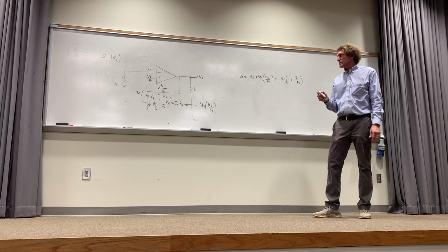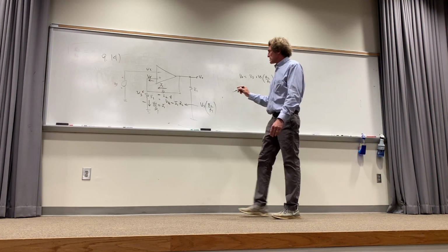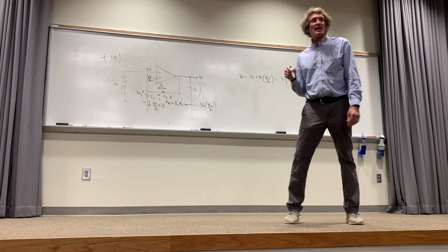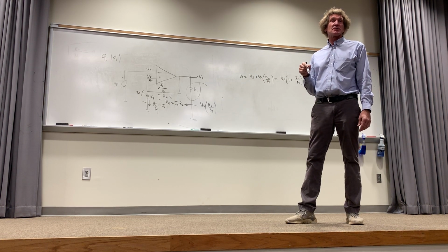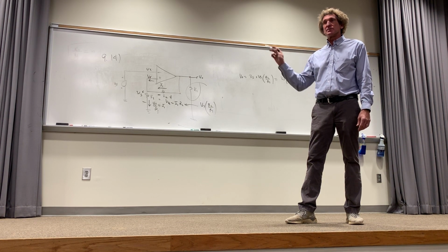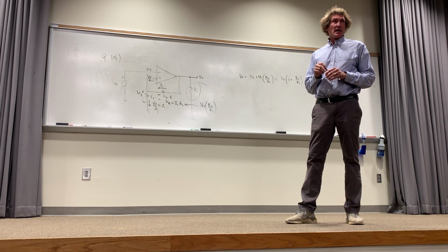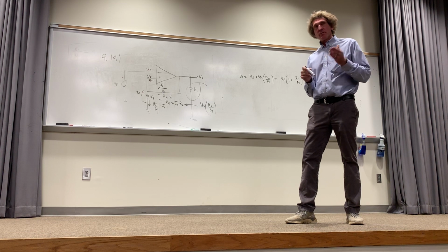That's standard. Here's the thing people do. This is a decoy. That's called a load resistor. That does not control that voltage, unless it's a short. But for any practical circuit, that would not have any impact on the output voltage. It's VS and the ratio of R1 to R2. Everybody got that? That's a straightforward problem. If you want, go ahead.